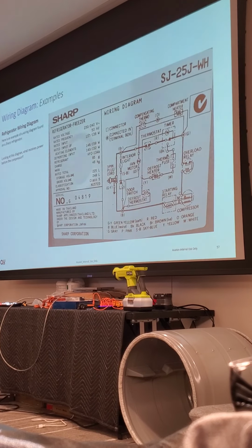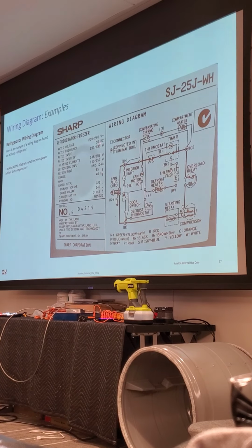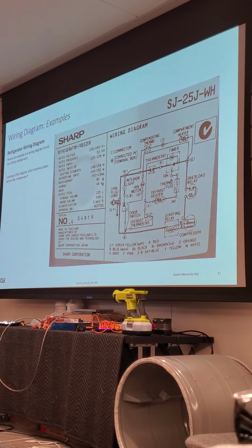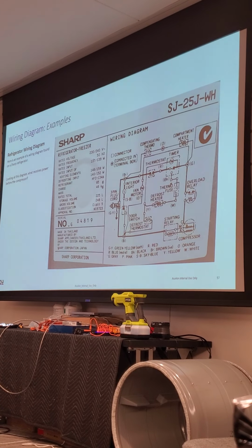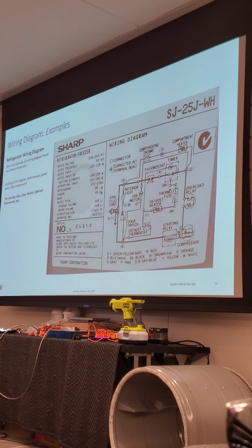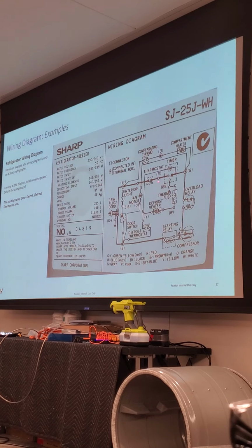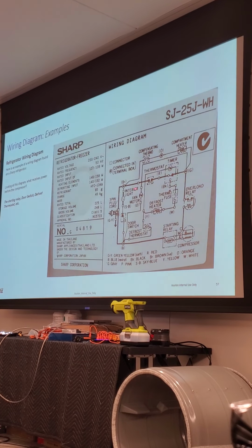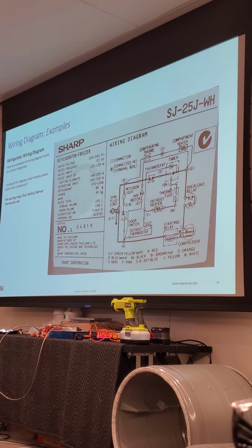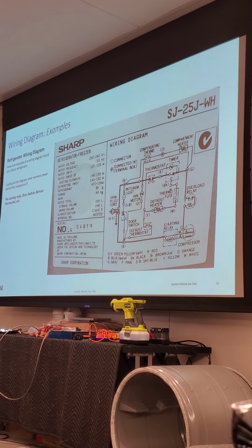And this happens to be what type of refrigerator? Using 50 hertz, 230 to 240 volts. This is one that you're gonna find from Sharp. It's gonna be a European market one. Okay? Your start relay, your door switch, your defrost thermistor, all that's going to be in your circuitry. There's your thermostat, your interior light, door switch. So that's the answer to that question of what we see before the compressor. Yep. The relay, door switch, defrost thermostat. Yep. Thank you.